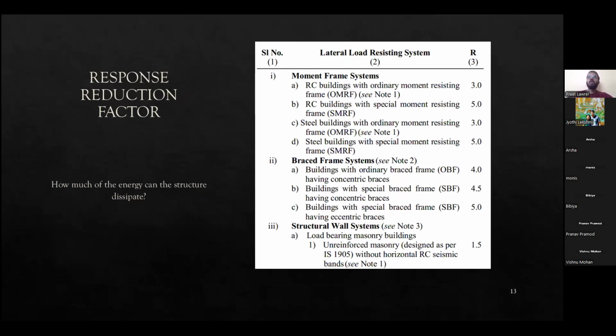So you know that the basic construction or the conventional construction of building is putting column, beam, and slab. That is the conventional system. And based on the type of reinforcement detailing, the way the stirrups are tied, the way the top steel and the bottom steel of beams are placed, the spacing in the column hoops, all these things decide whether your structure is an ordinary structure or a ductile structure. That is something which is specified by another code, which is specific for ductile detailing.